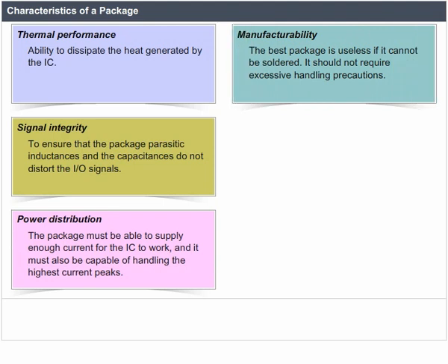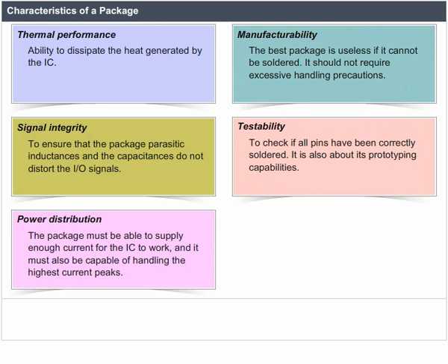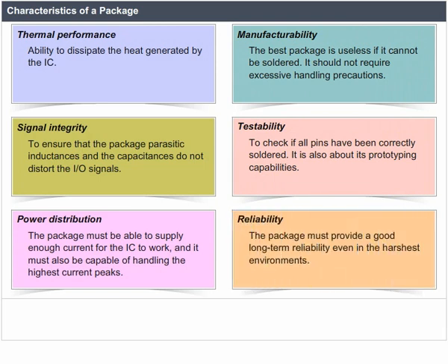Manufacturability: the best package is useless if it cannot be soldered. It should not require excessive handling precautions. Testability: to check if all pins have been correctly soldered. It is also about its prototyping capabilities. Reliability: the package must provide good long-term reliability even in the harshest environments.